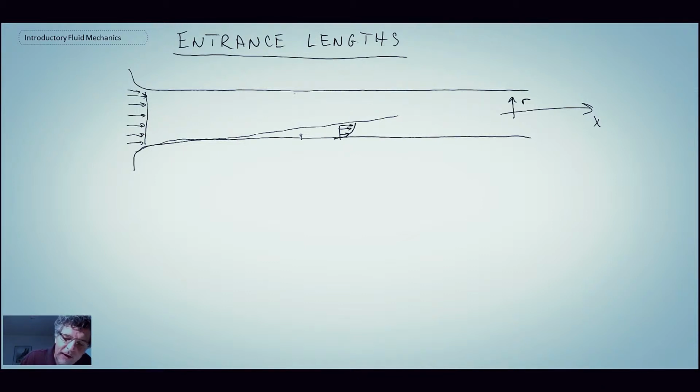And this boundary layer obviously is going to grow all the way around, so we have a round pipe, and so it's kind of coming in. And eventually you're going to get to a point where that boundary layer around the pipe meets, and that is when you have what we call the development of fully developed flow. So on the other side here, obviously we would also have a similar sort of velocity profile coming along, going from zero at the wall out to some free stream value, and it would be symmetrical.